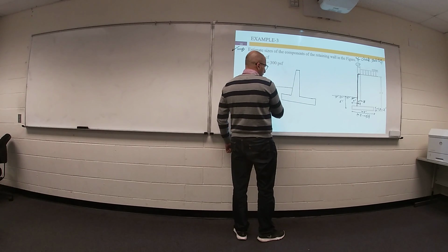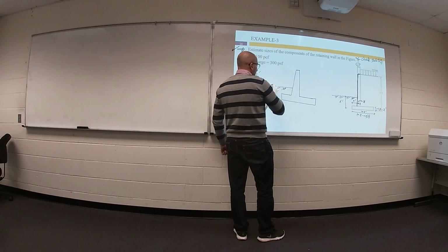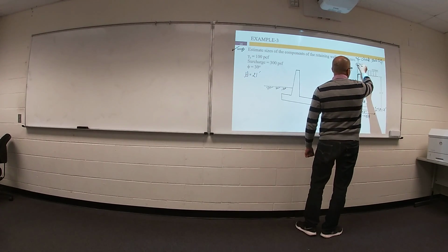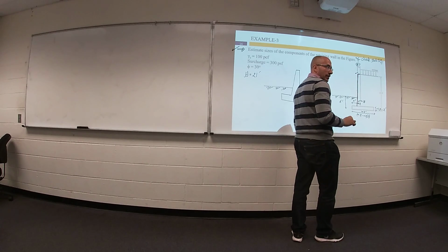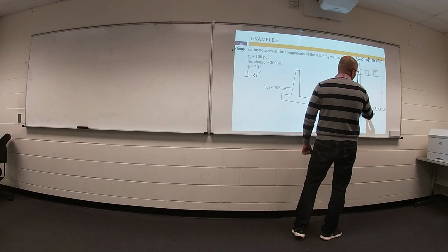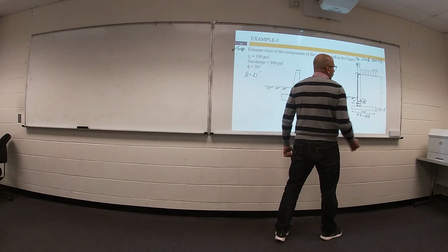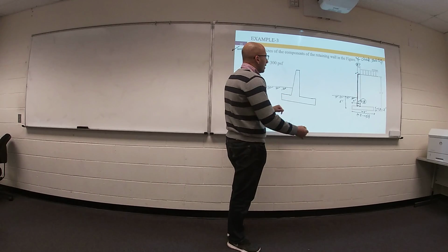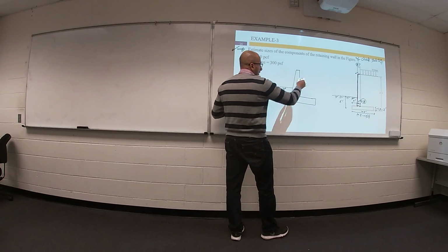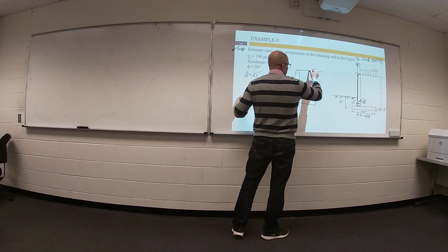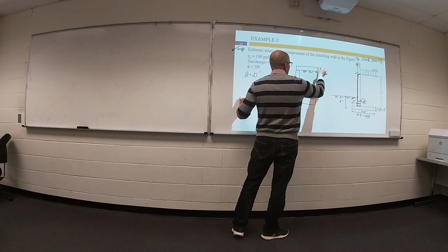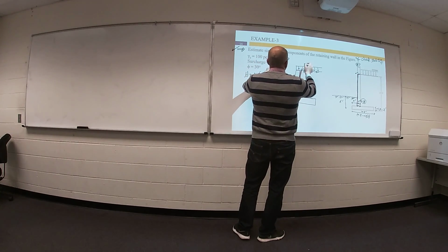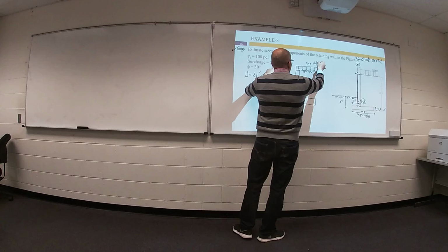So are we assuming that the stem is at an angle? Yeah, like this. Because 1 foot thickness is given at the top, and this thickness should be something around 0.1 h. So 0.1 h equals 2 feet. This one is given 1 foot. This one is estimated to 2 feet. That means I have variable thickness. Surcharge given. How much? 300 pounds per square foot.